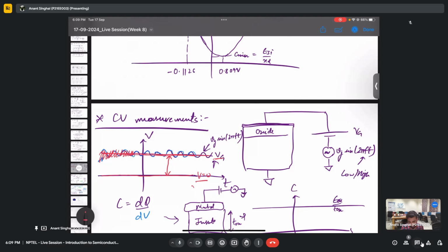Yes, sir. Then in that case, once the DC sweep has gone very fast, like a pulse, finally it will remain at that high value, right? Yes. Then in that case, the electron should be formed, right? I know, frequency, I'm talking about this AC signal frequency. So if the frequency is fast, then the thermal generation will not be fast enough. The DC sweep, don't compare it with the DC sweep. Focus on the AC sweep for this particular plot.